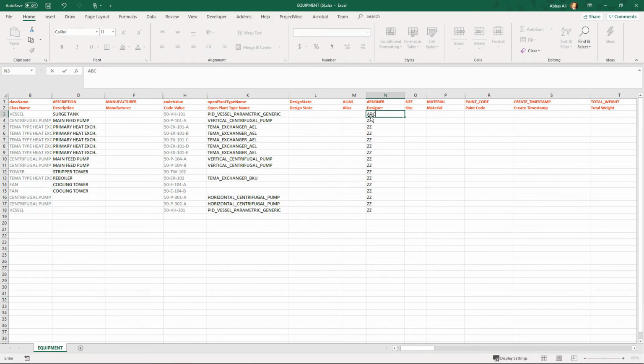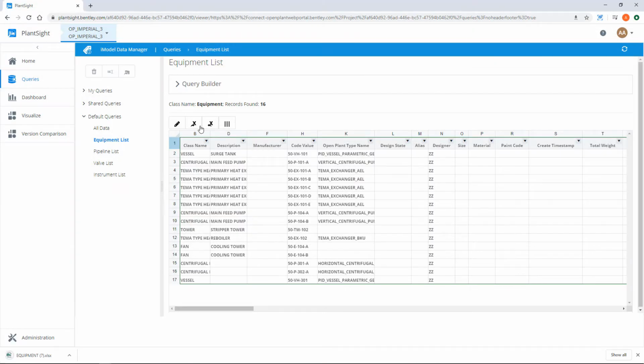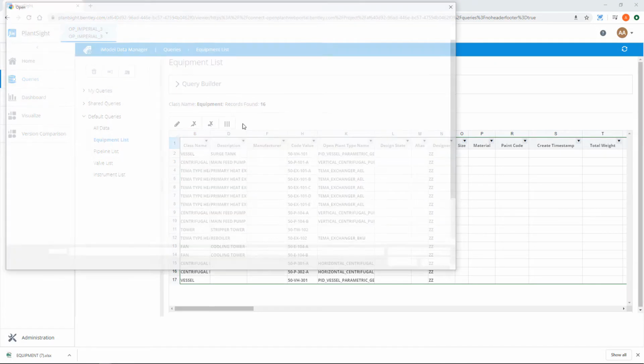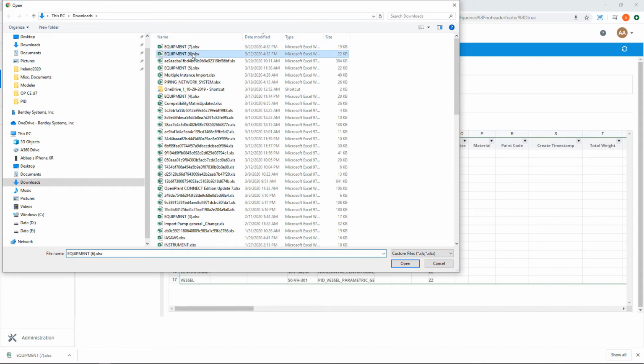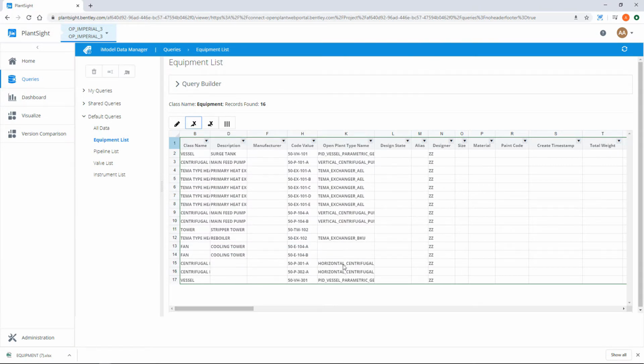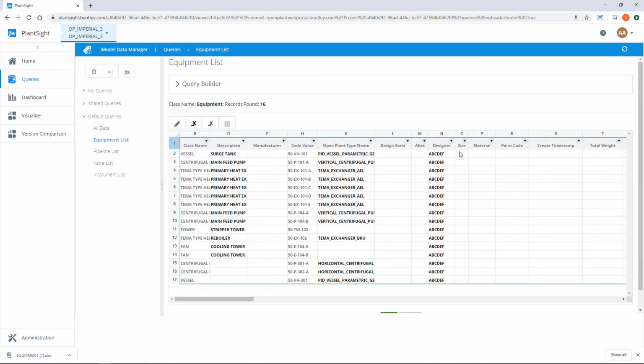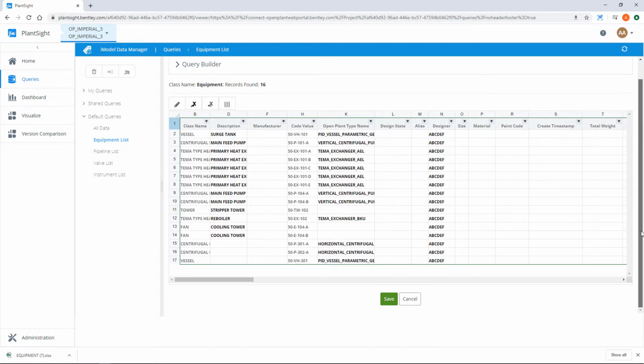The import button can be used to bring in the changes which are displayed in the grid in editable mode. Manual editing or somewhat Excel-like editing can be done in this grid and data saved to iModel. The new values will be synced to documents and design file once the sync operation is performed in client applications.